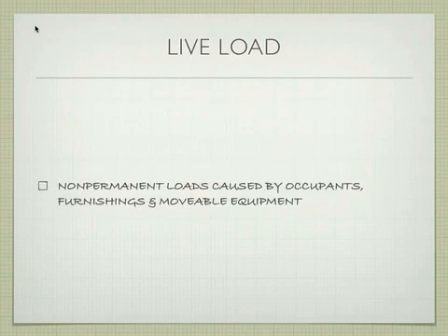So live load is anything that can be moved around by the occupants. These tables can be moved around. You can move your chairs around. We're in the building, we move around, right? That would be a live load. Does that make sense? Good. So it's just things that can be moved. It doesn't have to be alive. Your animal or your pet certainly would be live load, but the table is equally live in this context.